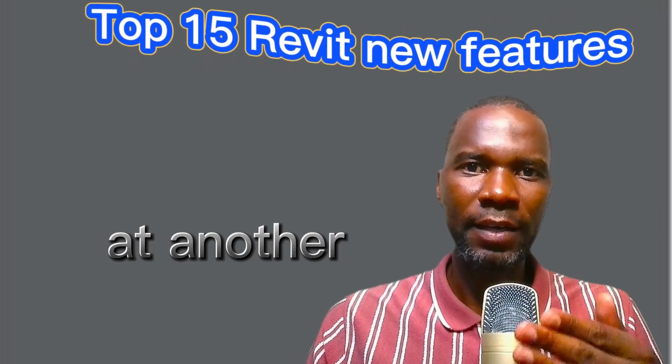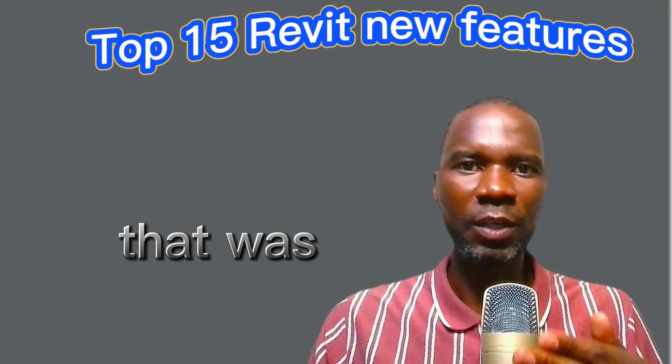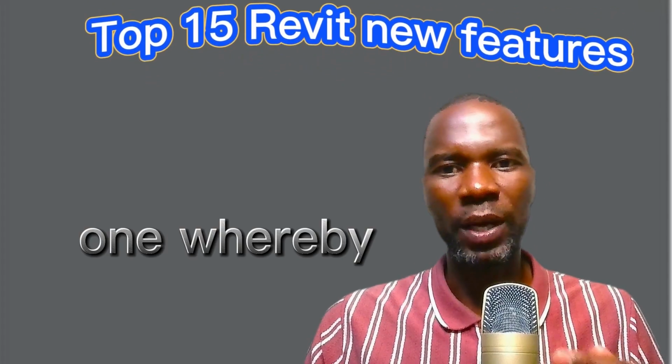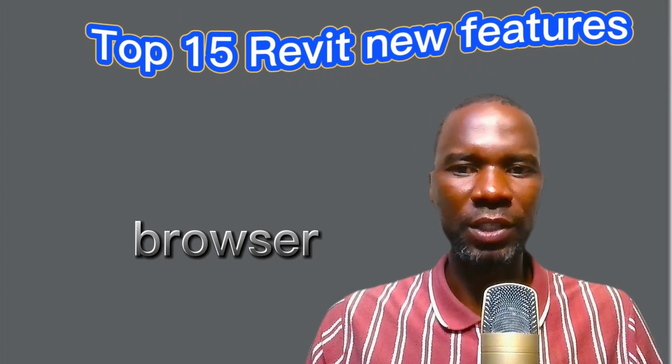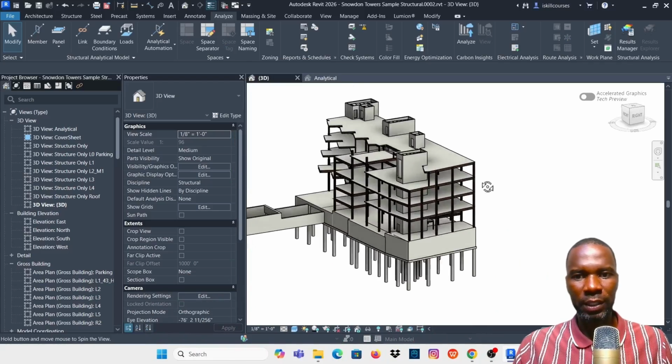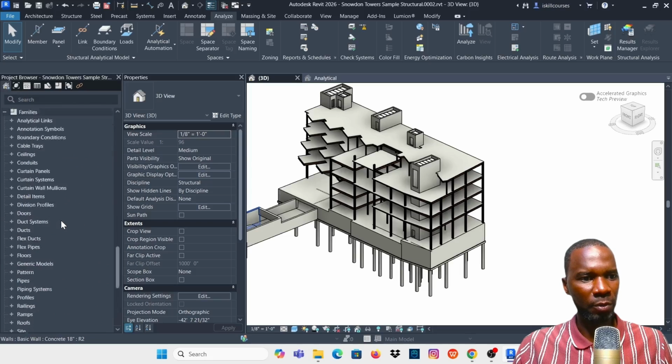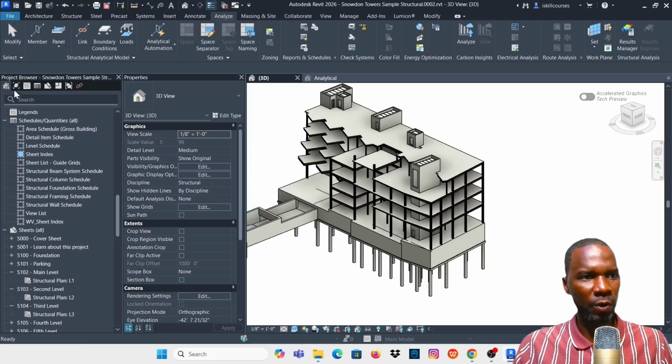Let's look at another enhancement that was introduced in Revit 2025.2. That is the one whereby you can filter the project browser. All right, so you see that again, we are going to use this model. If I come to the project browser, you see that you have several options here. If you want to show everything on the project browser, just make sure that you are on all. Then you can also just filter by views.